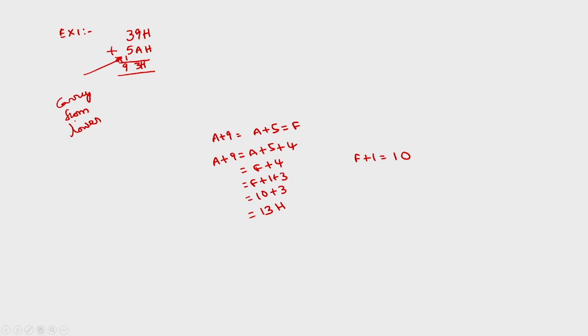This is lower nibble 9 and A. It implies the auxiliary carry flag is set. We can also check that there is no carry out of the MSB, so it implies the carry flag is reset. We can do this using binary also.